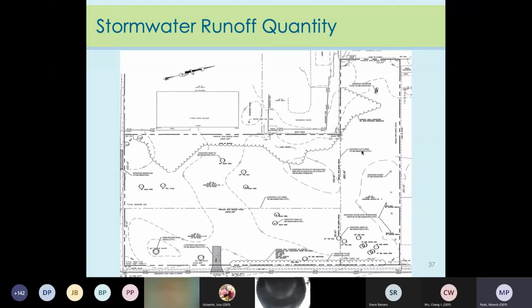So as you see here on this example site, the flow was evaluated and sheet flow directed primarily in a southerly direction here. However, we received complaints of flooding along the road lying to the east of the project and from the area northwest of the project. So it was determined that the drainage areas were not delineated correctly. Whether or not that was due to an incorrect evaluation of the topography is unknown, but this shows why it's important to properly evaluate it and delineate drainage areas.